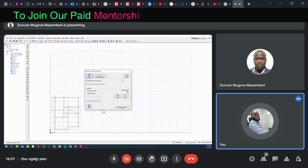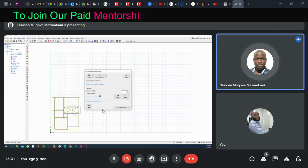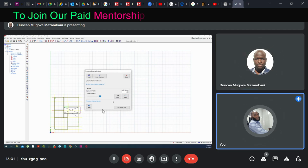Okay, now click on use color. Check that use color. Use the DXF color. Yes. Now click on import members.